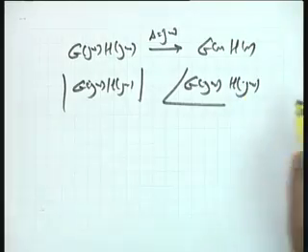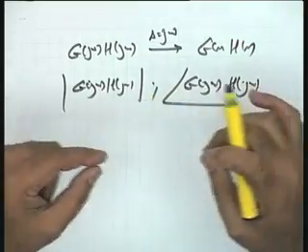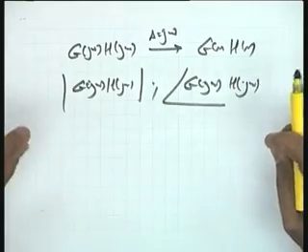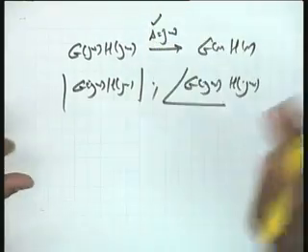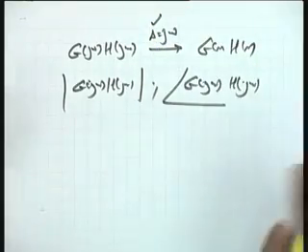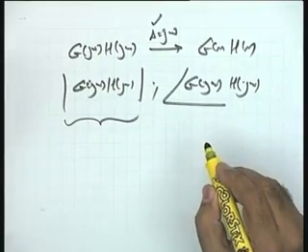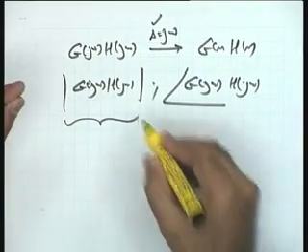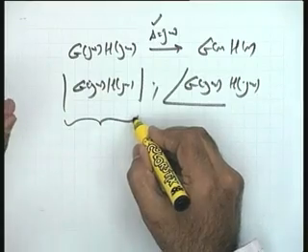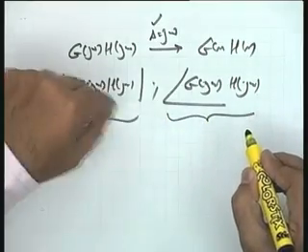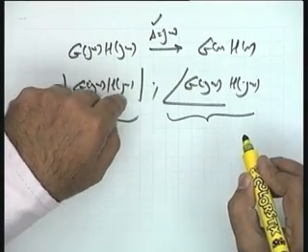With this information given to you, you can sketch, you can locate any point corresponding to an s point on the imaginary axis. But I know that this is the amplitude ratio of the open loop system when subjected to a sinusoidal input. This is the change in the phase angle of the sinusoidal input to the open loop system.